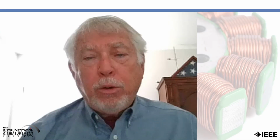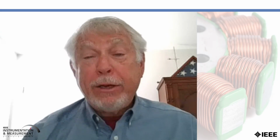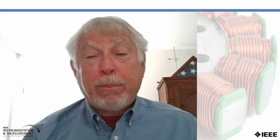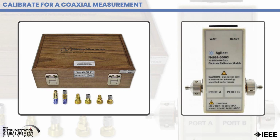To determine the 12 error coefficients, we measure some known devices, and by doing so, we can then calculate these error coefficients. Basically, most calibrations are performed either using physical devices such as opens, shorts, loads, and throughs, or more recently, you can use an electronic cal, or eCal, in order to make the measurement.